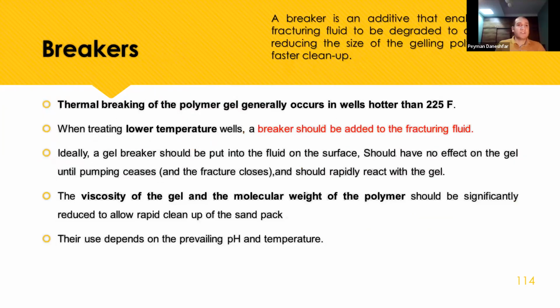Breakers, as I told you before: a thermal break of the polymer gel generally occurs in a well hotter than 225 Fahrenheit. So when we have a lower temperature in our reservoir, we should put some breakers in the gel to break in the wellbore and give us less residue of the cross-linked gel. When fracturing at lower temperature, a breaker should be added to the fracture fluid.